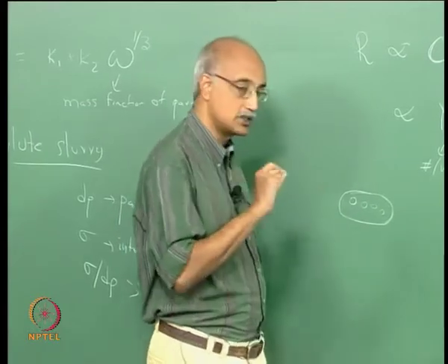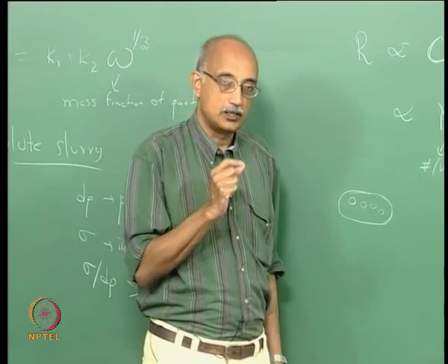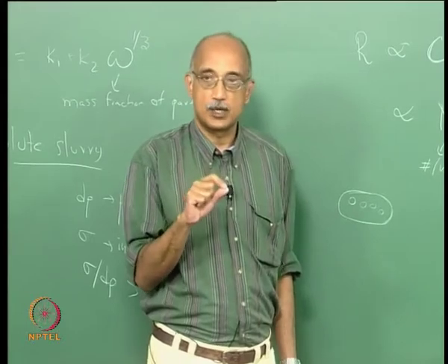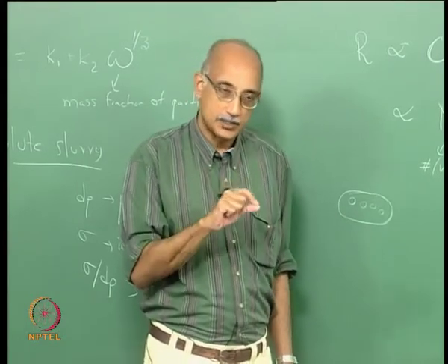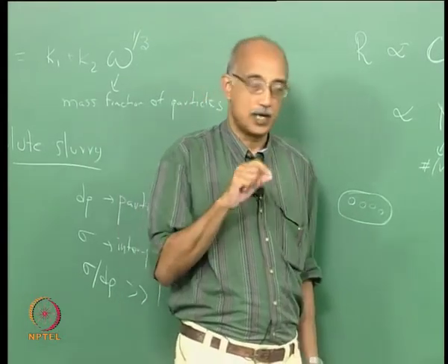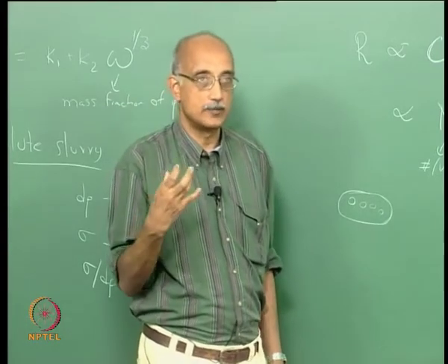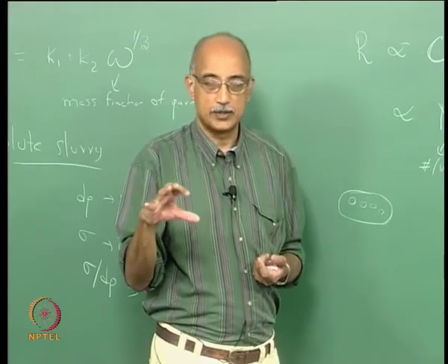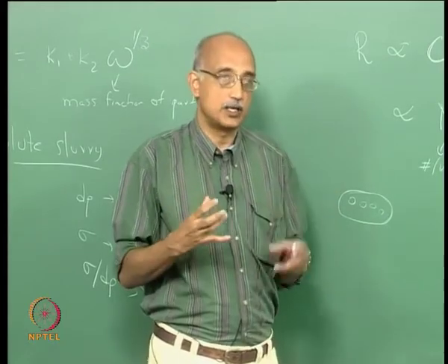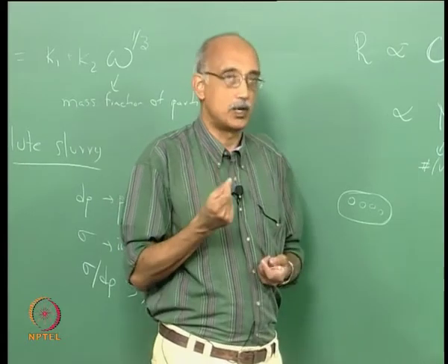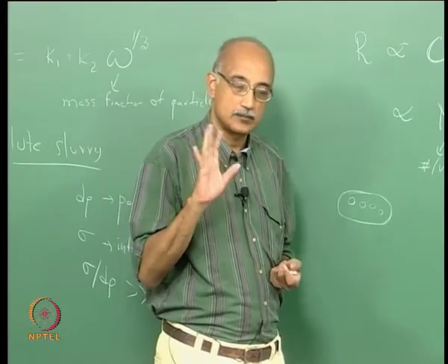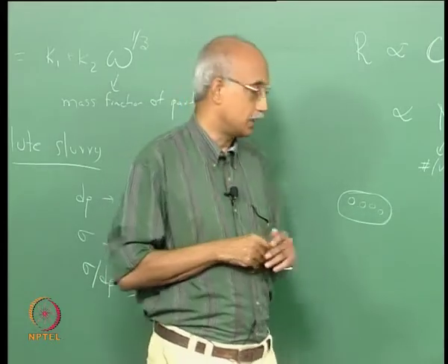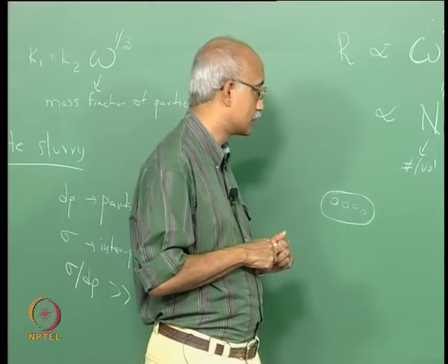So that is why there is essentially something to be gained by increasing the number concentration, by increasing the mean particle size in contact, but at the same time keep in mind that if you have a constraint that the total quantity of polishing media that is available to you is a fixed value, then you get more polishing area by actually making finer particles with that material. Okay. So the two are somewhat in conflict, but if you think about it, it is fairly straightforward.